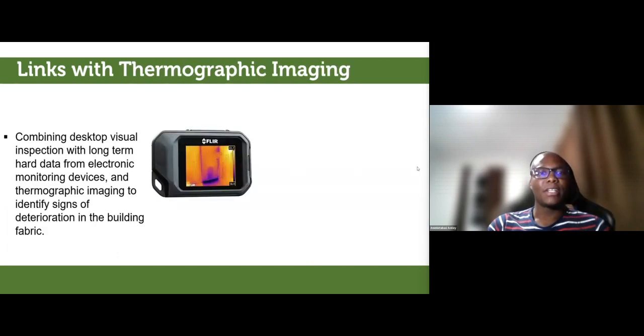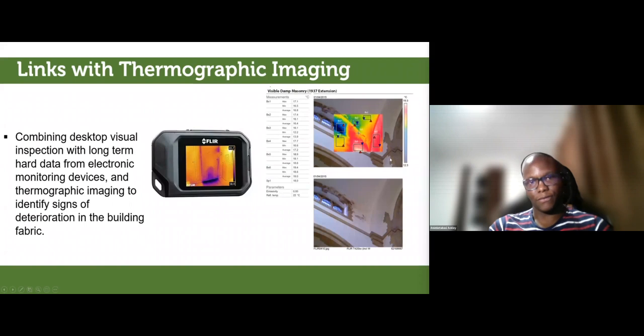Moving on to thermographic analysis. Thermographic analysis is the use of an infrared camera to take thermal images of the surface of an object. The thermal camera is a device calibrated to measure the radiation emitted from surfaces. The thermal camera turns the emission pattern of an object into a visible image. The result of a measurement is a thermal picture of the surface in which the different colors or shades of gray and red correspond to the various temperature levels of the target surface.